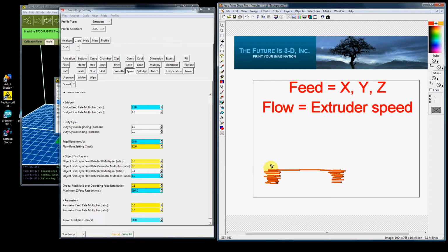If you were going slower, you'd start to get a sag, and your plastic would just sag. If you're going really quick, you're going to stretch that plastic across and bridge a lot faster. It depends on the plastic you're using and the temperature you're using. I would adjust the temperature to make sure you're not running too hot, because this setting works pretty good. But that's where you would set that.